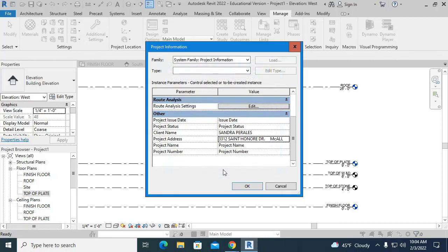Okay. Now, I gave you a big clue right there when I said, why is this important? It depends on how it's going to be used. I'm updating it here. Guess what? If my title block says who drew it and I put author, it will automatically read Javier Reyes because I told it here. If I put address on my title block, guess what? It's going to fill it in automatically because I've updated it here. Owner, right? That's something that goes on a title block. Who's the owner of these drawings or who are you designing for? It's going to automatically get updated.